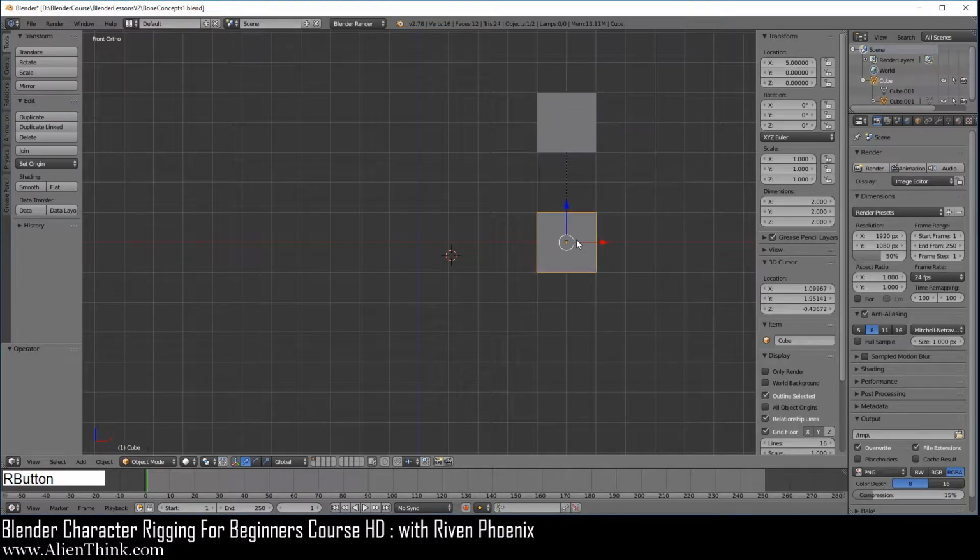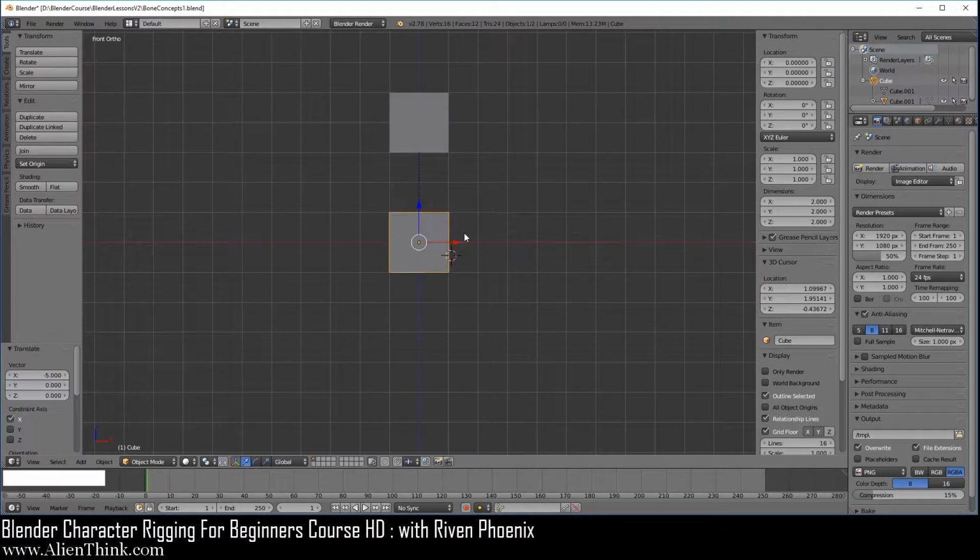Now, when we click on the parent and press the Control key down and move this object back to the center of the 3D grid, when you click on this object over here, you'll notice that it shows the same numbers that it had when it was over here. So when you do Alt G to reset the location, you'll notice that it ends up over here.